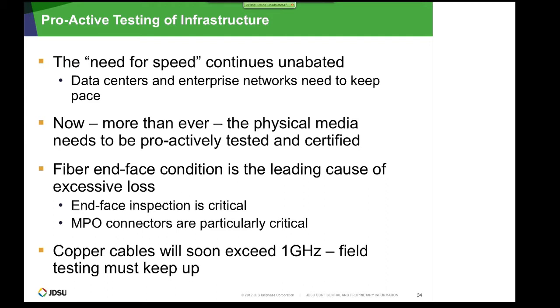Also, as was mentioned several times, MPO connectors are particularly critical, because if one of the fibers within the set of optical interfaces is contaminated, you have to disconnect the cable, and you have to perform inspection of all of them, and even cleaning all of them. It will take some time. It means one contaminated optical interface can impact the traffic on other fibers due to the necessity to clean and inspect it. Also, one contaminated MPO connector is impacting plenty of fibers.